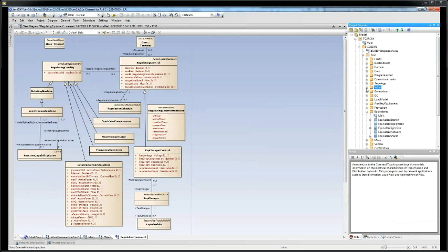Well, that's the way I would have interpreted the question: if you have different running arrangements you want to model, you should model the switching that puts those in place. So you would model that station in explicit detail with all the switches and disconnects and every piece of equipment located in it. If you mark certain switches as open, they would disconnect the appropriate devices. One other thing, which will be covered a little bit next week, is that once you get the switches in place, you could save configurations for different running arrangements. Correct.